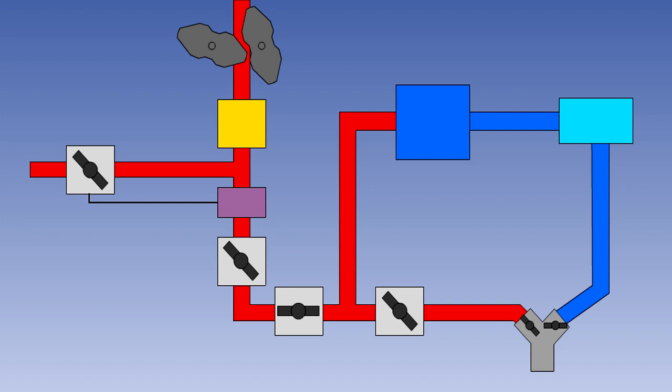Shown here is a simple schematic diagram of a cabin conditioning system using a Roots blower. Because of the design of the blower, the air comes out of it in short pulses. This can cause a thumping noise in the air conditioning ducts. The silencer helps to smooth out the airflow, reducing the noise.